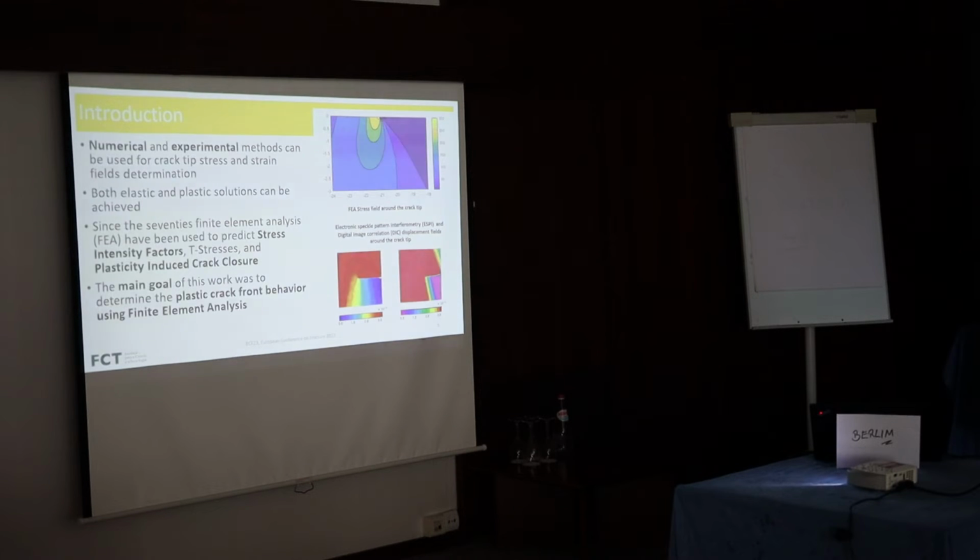In terms of the introduction, as you know, we can predict the crack tip stress and strain field determination using numerical and experimental approaches. In this study, we use a numerical approach. Both elastic and plastic solutions can be achieved, and using finite element analysis, we can predict the stress intensity factors, the T stresses, or the plasticity induced crack closure.